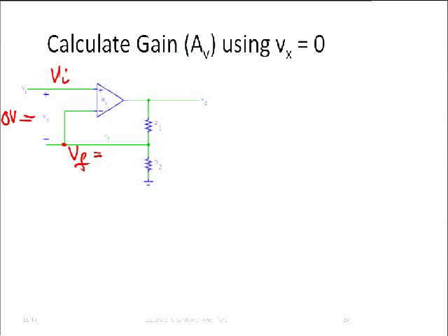Vf is equal to Vi, right? There is no difference between Vi and Vf. Well, then they are the same, right? So why are they the same? Well, it's because we have this negative feedback loop, right? There is no wire or so that sets that. No, it's the operational amplifier together with the negative feedback that somehow managed to do it that way. And the math tells us that it does it that way.